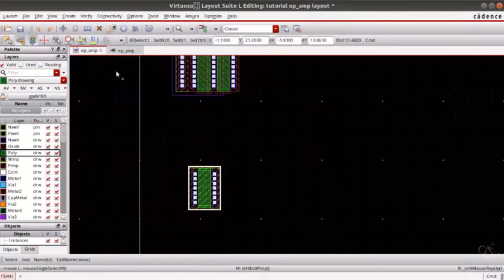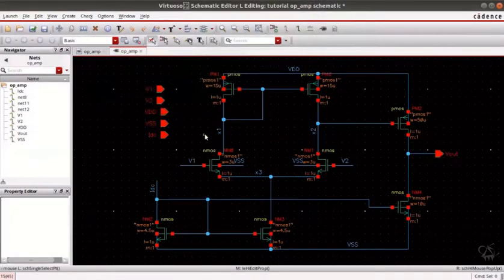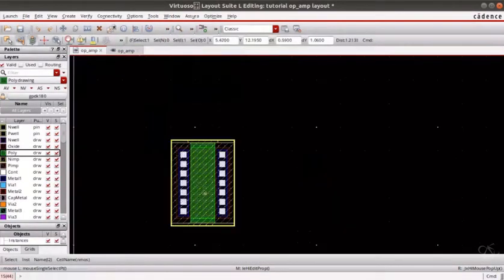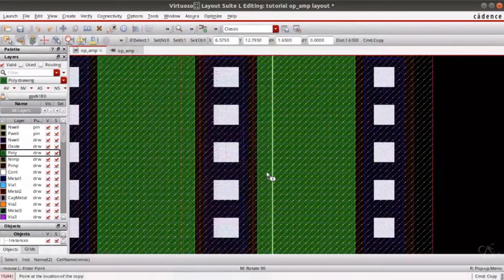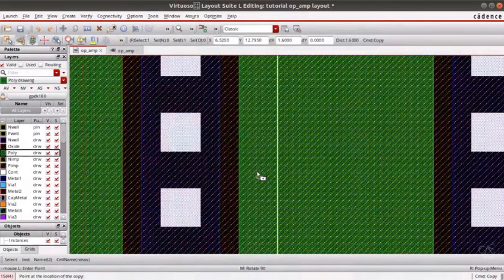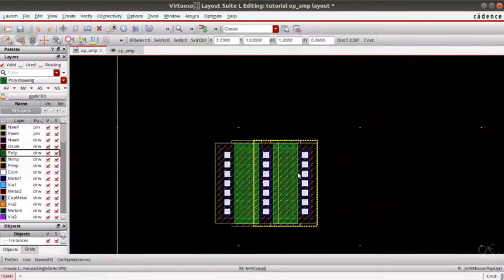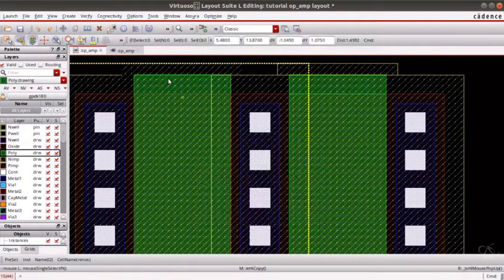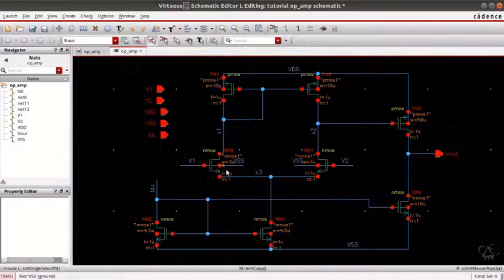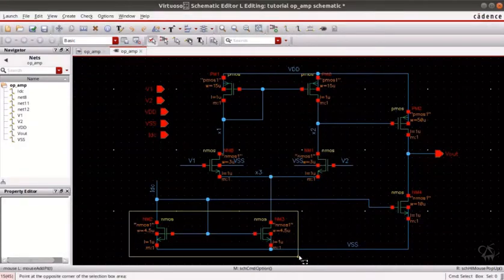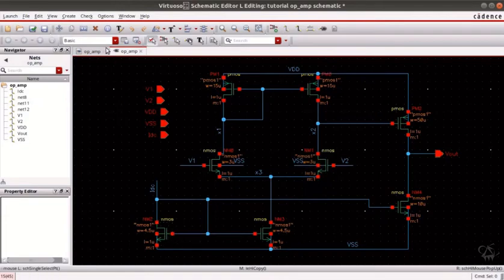So coming to these two, as you can see here, X3 is again common, so we can overlap them. So it becomes X1, X3, X2. So now let us place these two NMOSs, width of 4.5 microns.